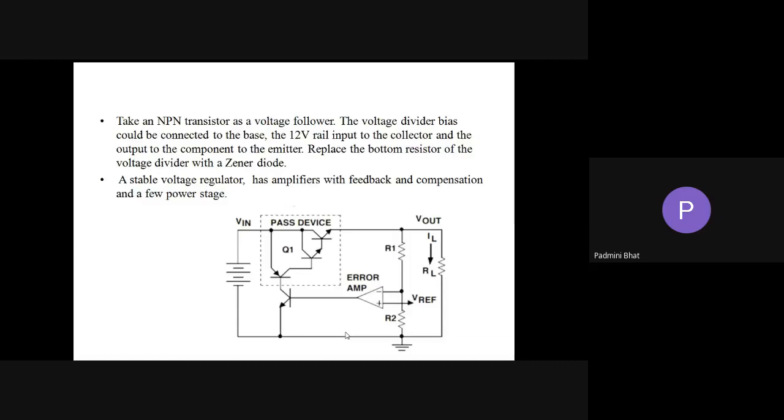Now that difference voltage will generate heat, because the energy has to go somewhere, in one form or another, so it comes out as heat. So this is one disadvantage of the regulator, though not the major one. It heats up if the difference between the actual input and the present input is too high. So even the regulator has a range. Only within these differences of the input will it work. After that, the performance is not accurate.